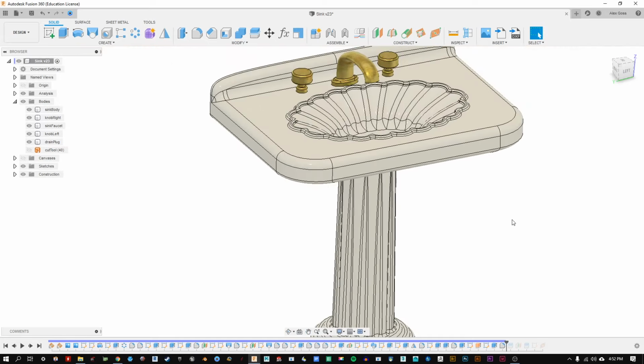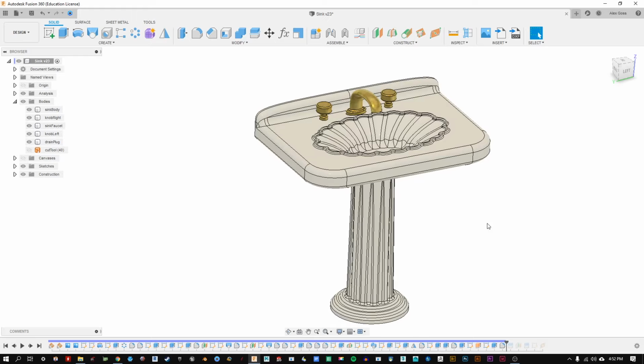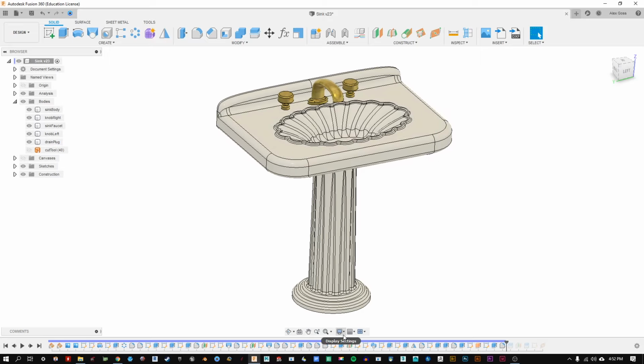But what a lot of them do is use some of your computer's resources, your hardware, to make things easier on the eyes. And they are potentially costly if your computer is already using a lot of its resources, or if it has few resources to give. These are going to be harder on your computer in running Fusion. Now that last one I clicked off, anti-aliasing, if you can run any of them, I would recommend running this because it really hurts my eyes to see these jagged lines.